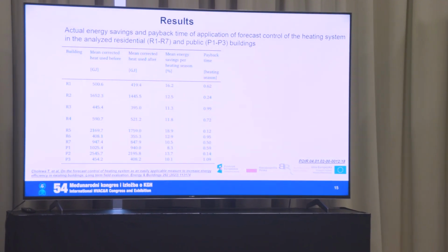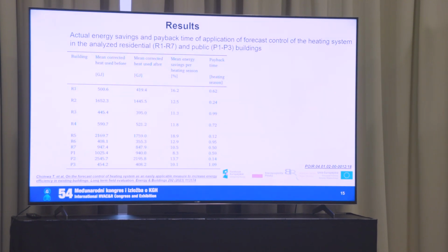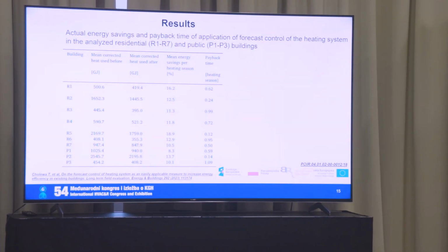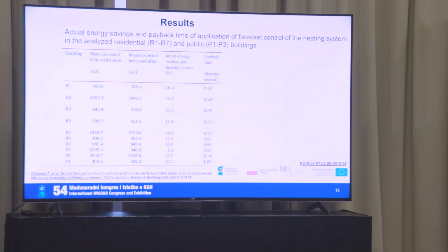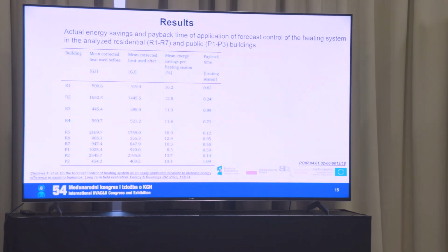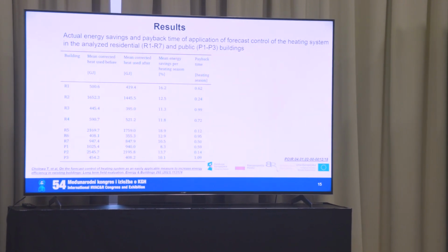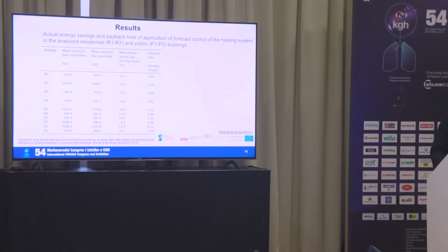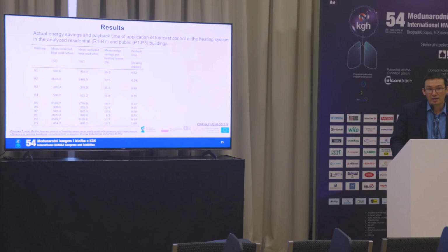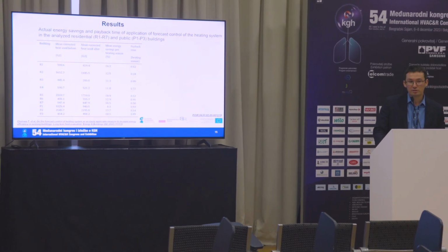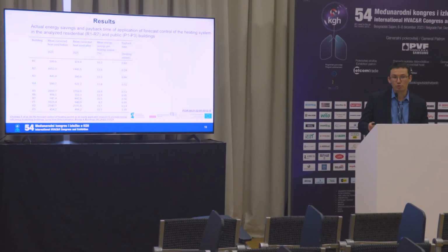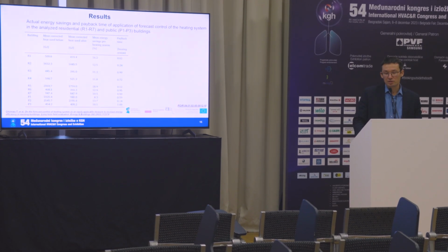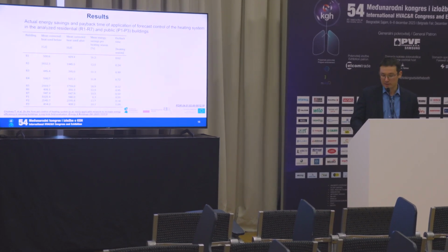Based on this, you can see that the energy savings are from 8% to even 18%. And with this kind of measures, you can see that the payback time is very low, around and below 1 heating season. So it is very good measures how to increase energy efficiency in existing buildings.